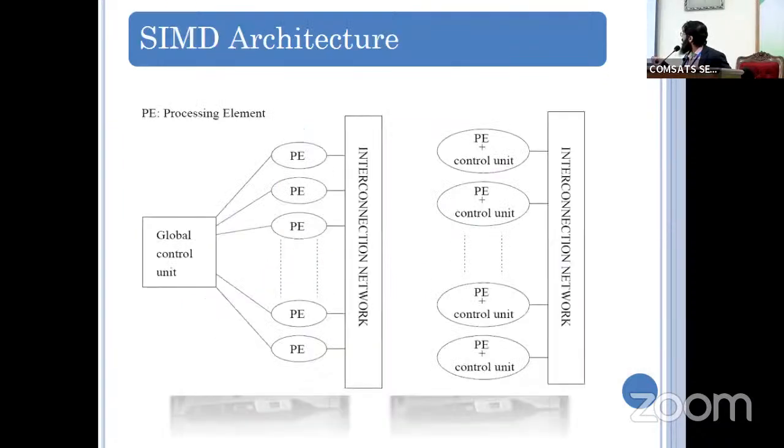And the SIMD architecture is the classical array processor. In an array processor, normally you are not dealing with control things. There are fewer if conditions. We have more loops, more data, data intensive computing. So for that part, we don't have a local control unit. We are not using a CPU where we should have a separate control unit. Instead, we have a separate global control unit. We don't have a control unit in all these processing elements, while in normal PCs and distributed systems, we have simple processing elements and then control units. That's how we can decrease the cost and increase the performance of array processors.